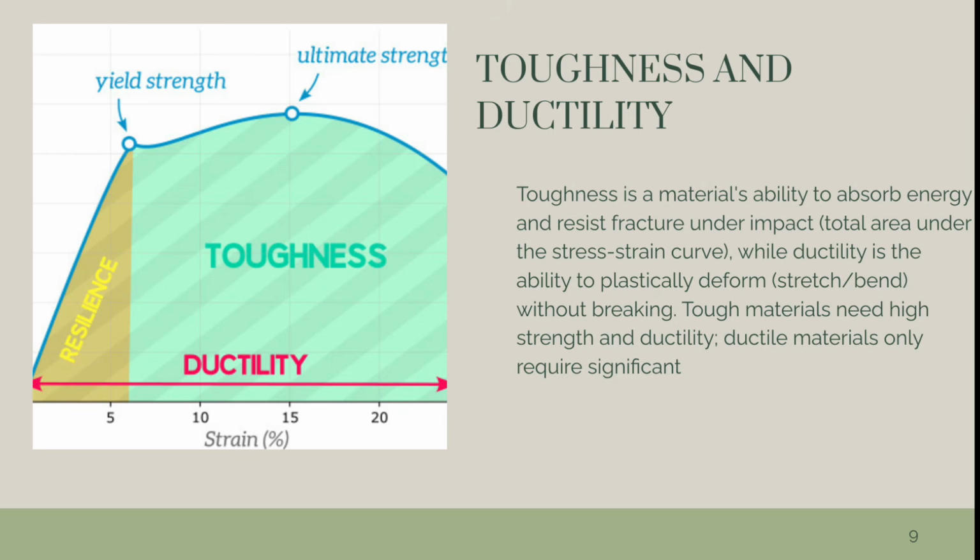Ductile materials, including structural steel and many other metals, are characterized by their ability to yield at normal temperature. For example, low carbon steel generally exhibits a very linear stress strain relationship up to a well defined yield point.